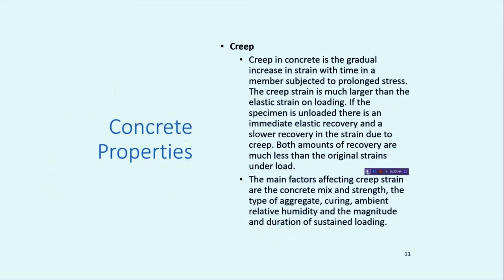The fourth one is creep. Creep in concrete is a gradual increase in strain with time in a member subjected to prolonged stress. Okay, so if you put stress yang lama, maksudnya the load is going to be there for a very long time lah. So the creep strain is much larger than elastic strain on loading. If the specimen is unloaded, there is immediate elastic recovery and a slower recovery in strain due to creep.